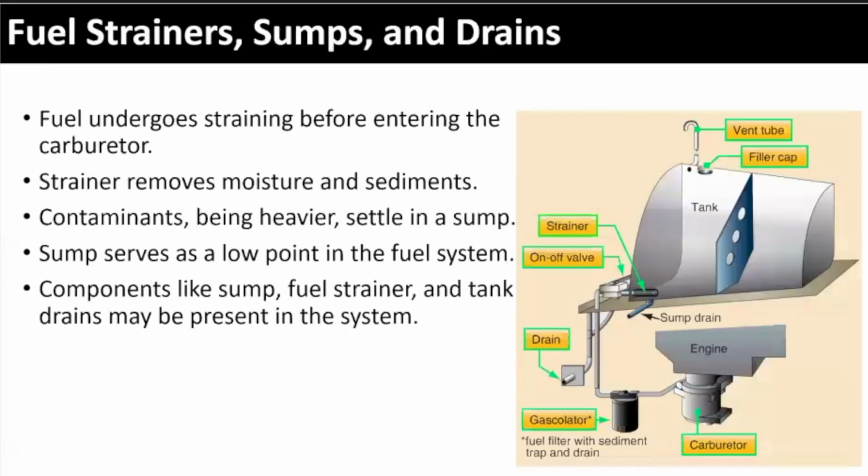Let's get to the diagrams here. Okay, it goes through a strainer. The strainers remove sediment, may remove water, depending on the system. The type of strainer that you have can collect the water at the bottom of the strainer and not get into the fuel, into the engine. But we've got a couple of different things on the plane. I like this diagram. It's got everything in a very simple view.